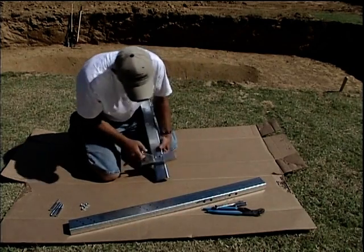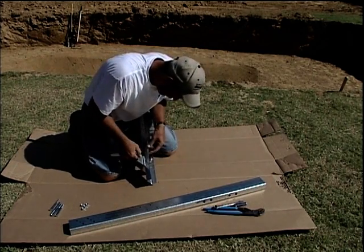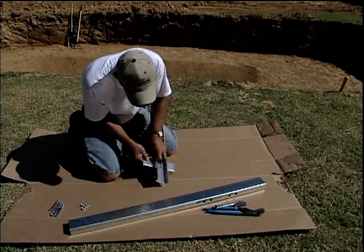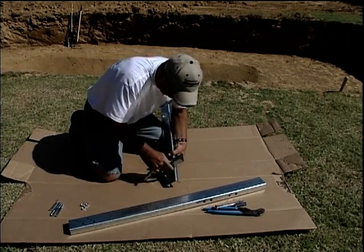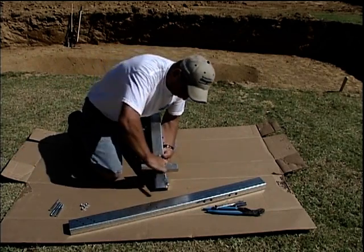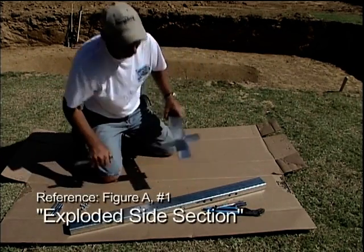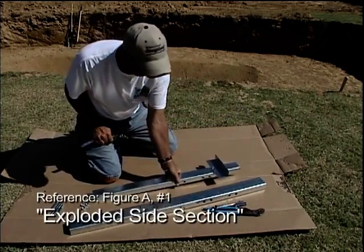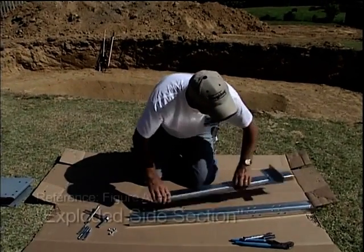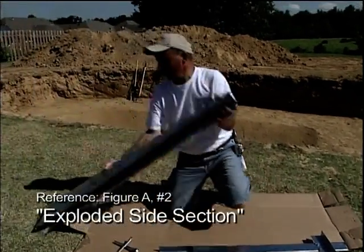To begin the assembly of the exploded side section, keep in mind that the orientation of the skid plate is vital to the strength of the structure. Attach the skid plates to the bottom ground support using 4 1/4 20 by 1/2" long bolts and 1/4 20 hex nuts. Please refer to Figure A, Number 1, Exploded Side Section in your assembly guide. Then, position the top ground support. Please refer to Figure A, Number 2, Exploded Side Section in your assembly guide.